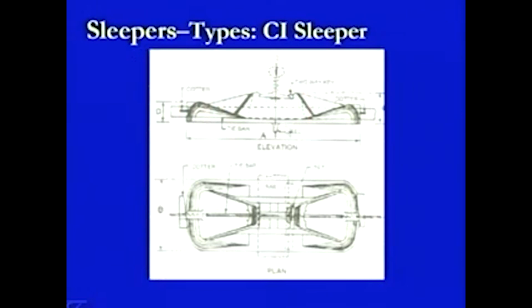This is one of the diagrams of CST9 sleeper. In this case, what we see is an inverted triangular plate which is being used. Then there is a flat plate condition which is used here, and a sort of a cup being placed on this side. So, this is the elevation of the CST9 sleeper. In this one, the rail section is being placed here. So, the grooving is being made, and we are using a two-way key which is inserted at this location, so that this rail section can be placed and held at its level.